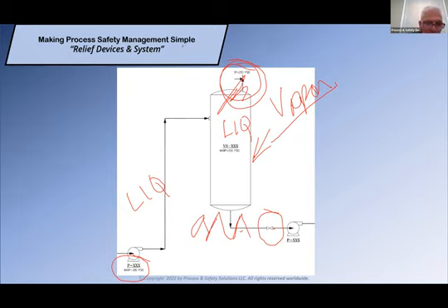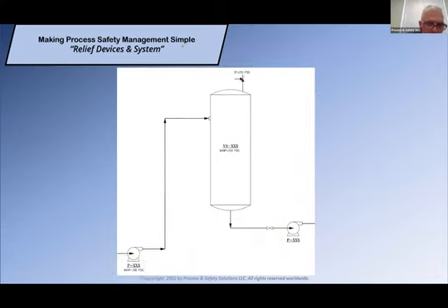Now, if this 280 down here was not looked at, let's say, for example, and we see this quite often, the original design is 240. If I looked at the scenario, and this was 240 PSIG maximum pressure, then I would say, okay, the relief valve is set at 250, this is 240, so that scenario would not be one that I would size this relief valve to. It would be some other scenario, because this pump could never cause that relief valve to lift.